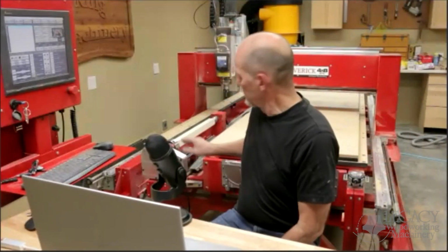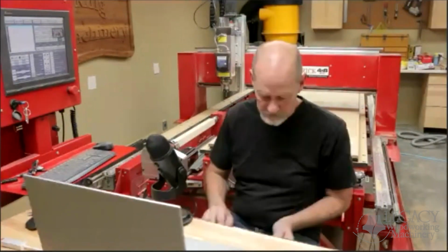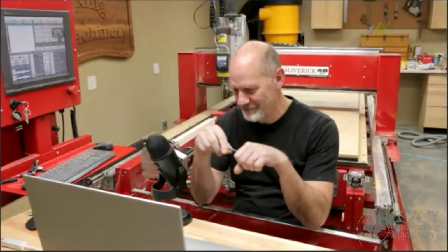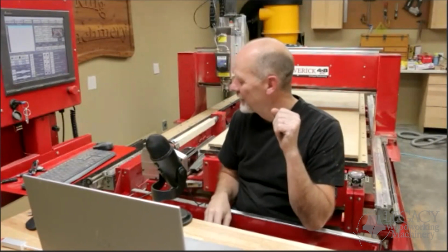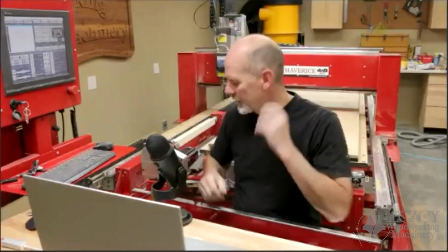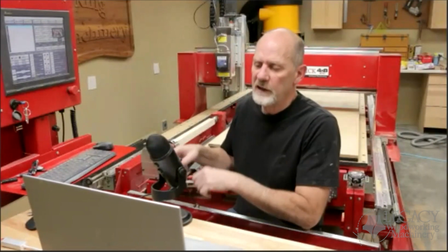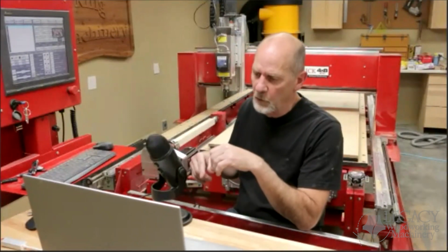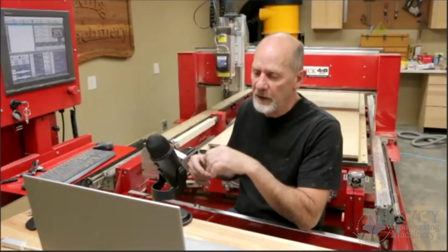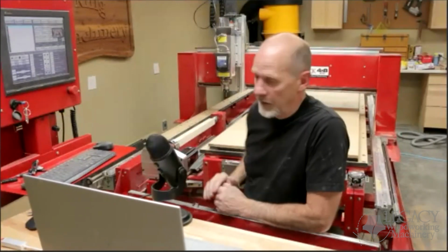Okay, so a couple of things. I'm using the 4-jaw chuck, obviously. At that far end down there, I took an awl and I just eyeballed it, and I put a hole in the center of it. That part's going to be tapered, so if I'm off a little bit, it's not really critical, but I got it centered the best I could. When I tightened up the handle on the tailstock, I rotated until the part was secure. I don't want to over tighten it, so I just brought it up till it wouldn't move, and then the handle was straight up. So I disengaged the handle and rotated it down out of the way so that I can clear it.